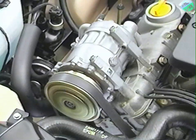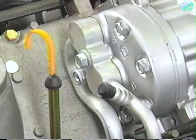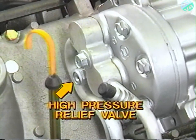The compressor on Premiers and Monacos uses a wobble plate to drive 7 pistons. On the compressor head is a high-pressure relief valve. The relief valve vents refrigerant to atmosphere when excessive pressure develops on the high side of the system.